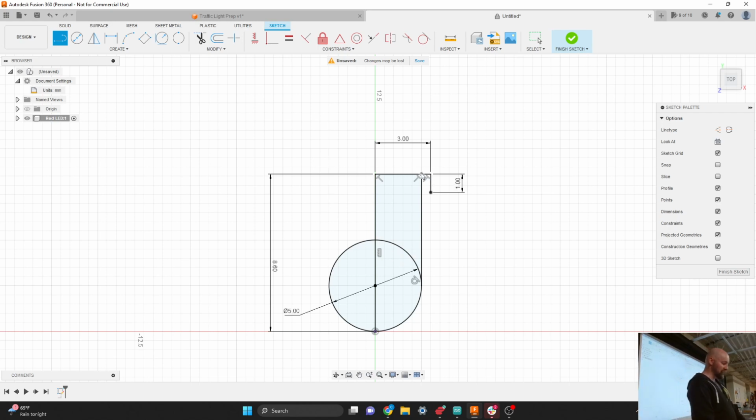So I did mine the fancy way, where I hold down a magical button on my keyboard. If before I made my line, I hold down the shift key before I click to place the first point of my line on that circle, now it is forcing it to be tangent. I'm continuing to hold the shift key down as I move my mouse around, and you can see the line is always going to be tangent. It's adding that tangent constraint right away.